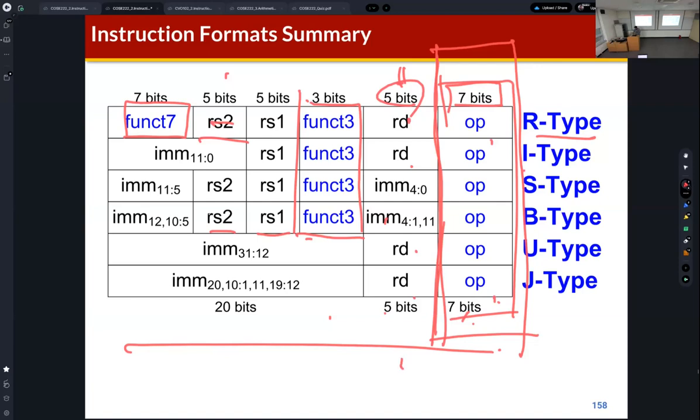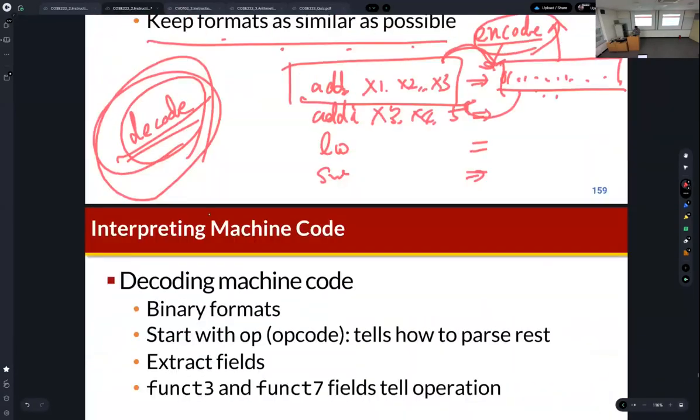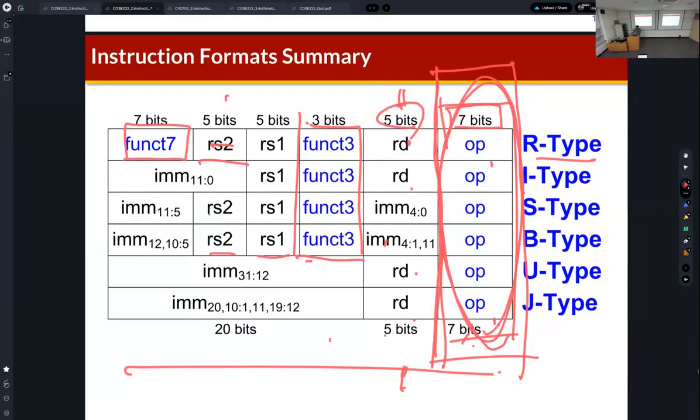As you can see, this is the summarized encoding rule. The processor first checks the opcode field, and then the processor can know which type of instruction is given, like load, arithmetic immediate, or arithmetic instructions. So the processor can know the type of instruction, like I-type and S-type. Then, if the processor knows the type of instruction, it can decode the additional fields.